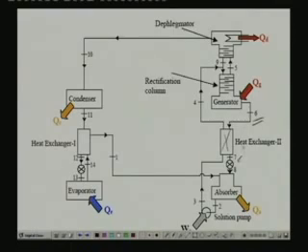Since this is still at high pressure, its pressure has to be reduced to that of absorber pressure. That takes place in this solution expansion valve. So, at the exit of the solution expansion valve you have low pressure weak solution, that is 0.8. This low pressure weak solution now comes in contact with the refrigerant vapor coming from the evaporator, and absorption takes place, and that is how the solution circuit is completed. So, this is the working principle of ammonia water system, and you can call it a single stage ammonia water system.